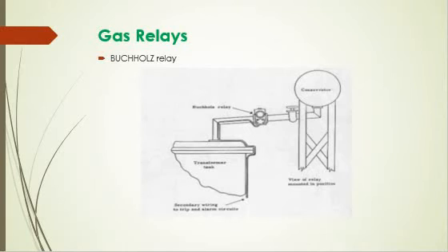The very slow accumulation of gas may be a tolerable operating condition with some transformers. A flashover in the transformer will cause a pressure wave to travel through the oil and will compress the flexible bellows in the bottom section of the relay. The air inside the bellows will compress and will cause the flexible diaphragm to actuate the micro switch to initiate tripping of the transformer. The relay described in this is the Buchholz relay.